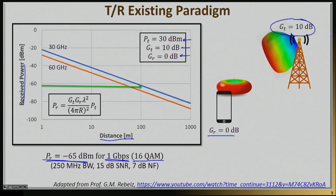So if you look into the Friis transmission equation, you will find out that roughly speaking, if you're operating in one of these bands, 30 or 60 gigahertz, which are two of the millimeter wave bands that 5G will exist on, you're basically covering distances in the order of 10 to 100 meters if you must maintain a -60 dBm power range. So as you can see, the distance, once you move to millimeter wave, basically drops dramatically.